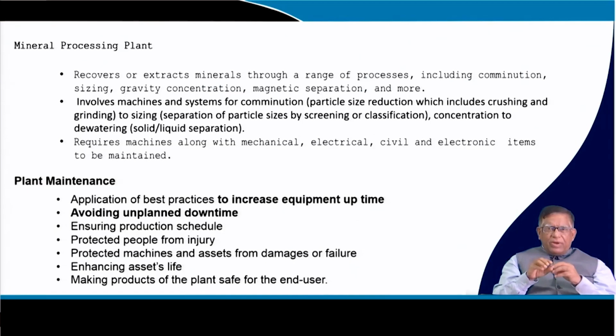Wherever you have the working member, the working member will have a motion which is brought from a source of energy. So there are different types of drive, and then there would be either a linear motion or a rotary motion. Wherever there is rotary motion, there is a bearing. In linear motion, there is sliding motion. So the surfaces of these different parts are subjected to wear and tear.